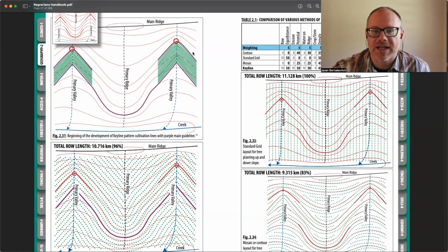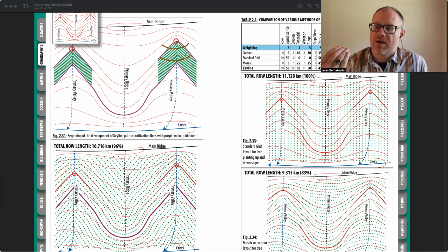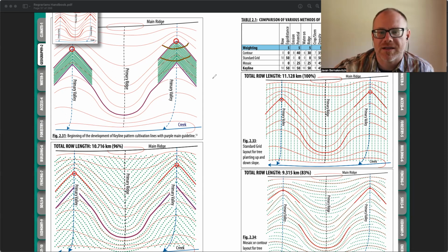So if we excavate here, you can see how close these lines are. Let's say we change this into a pond instead, and let's say we take, I've got to put on my drawing tool, a dam wall here. The amount of volume of water we get there is more than, let's say, if we put it up here, because of the amount of incising we have of that valley. So this has also been a place to find where that ponding potential is.